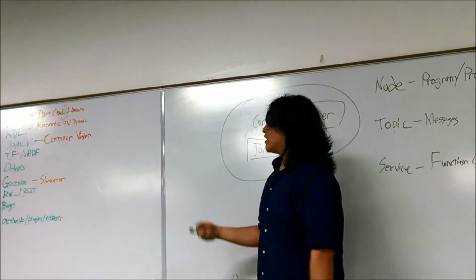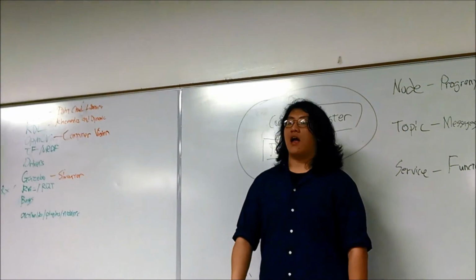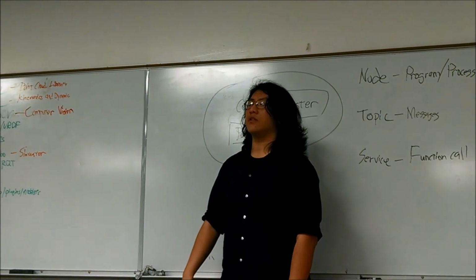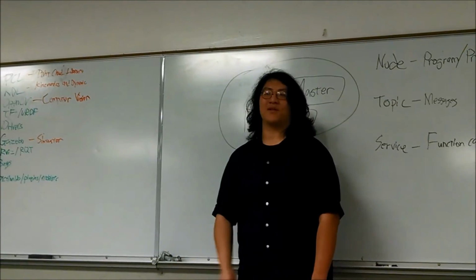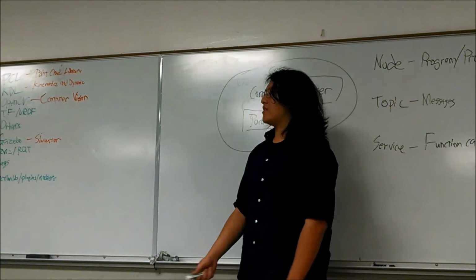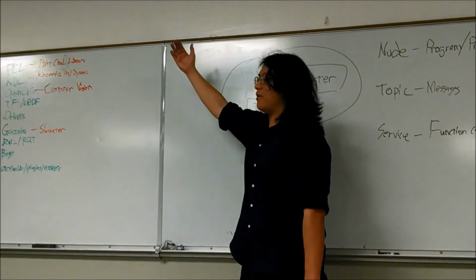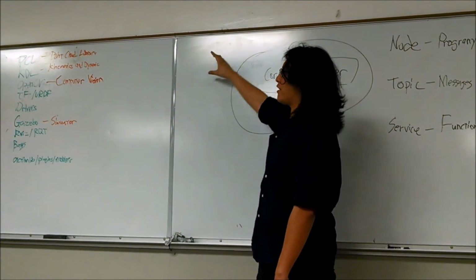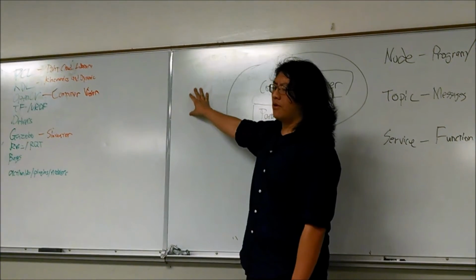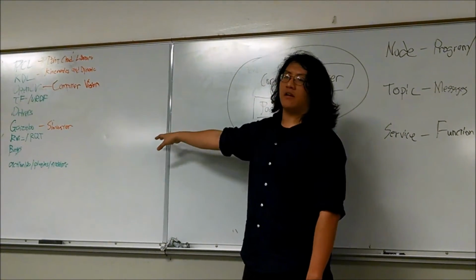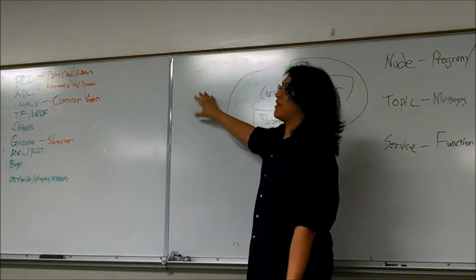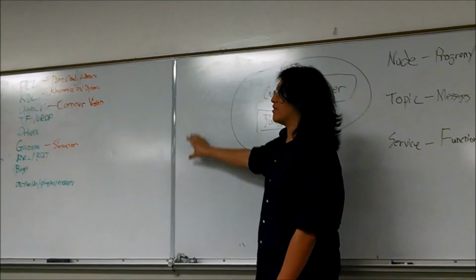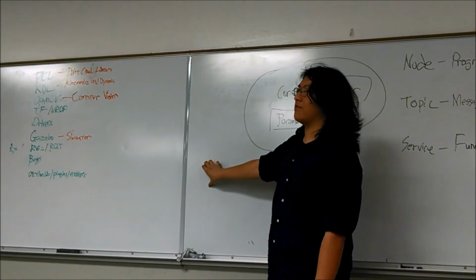A use case example of a nodelet is I have a bunch of nodes that do something to an image. Like IGVC last year, we had a node that read an image from your camera. Then there was a node to, I don't know, run Canny edge detection on it or something. And then another node to run Hough lines on it, and another node to do ray tracing, etc.